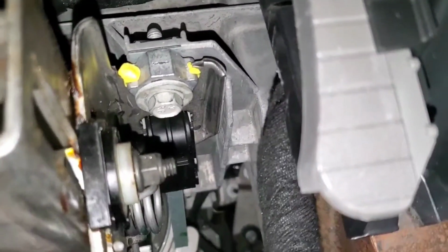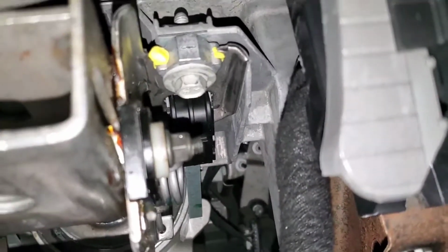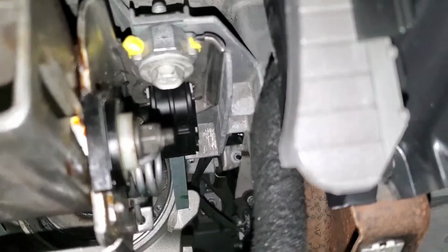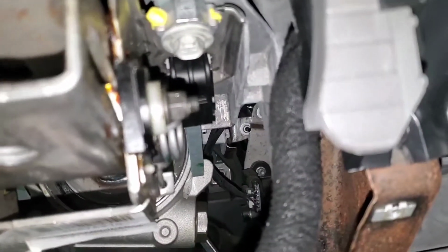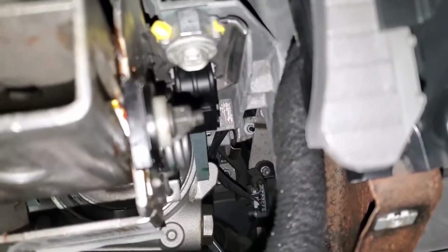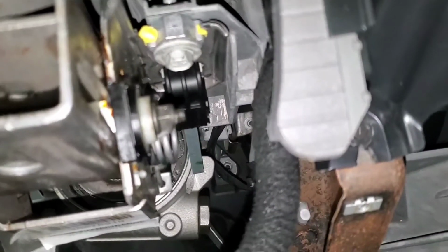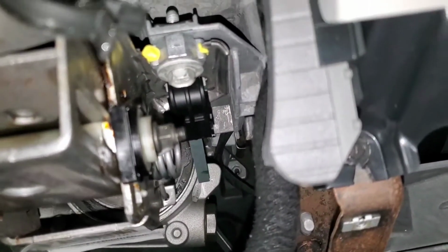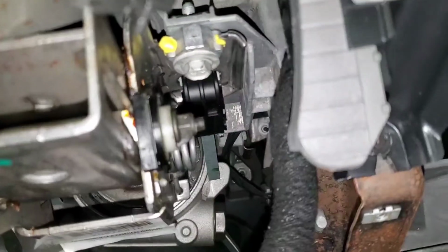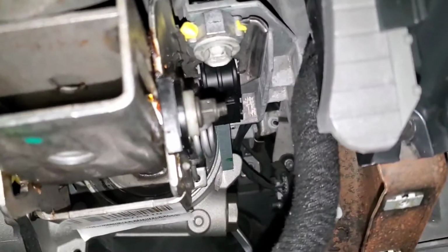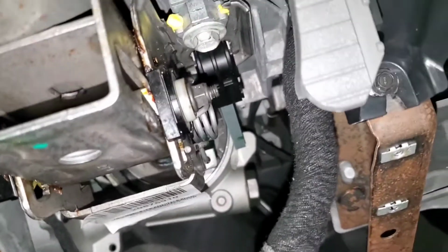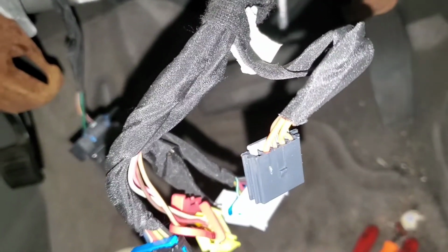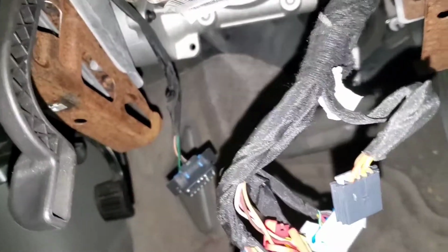Because this is an energy absorbing joint, if the driver hits the steering wheel in an impact, it's supposed to slide down and break away. So it's critical that those are torqued to 20 foot-pounds. Any tighter, and there'd be more resistance to sliding.